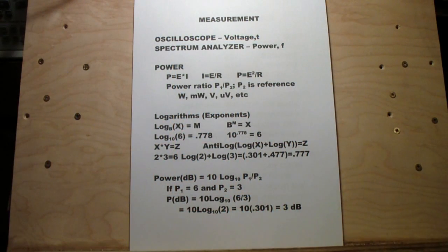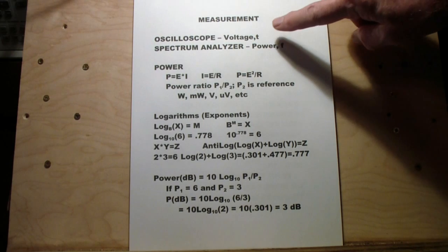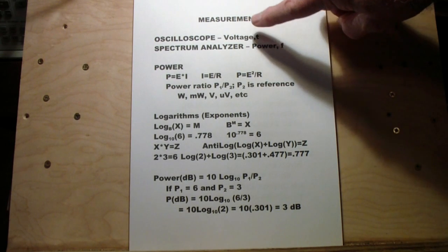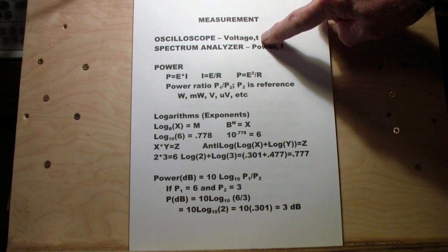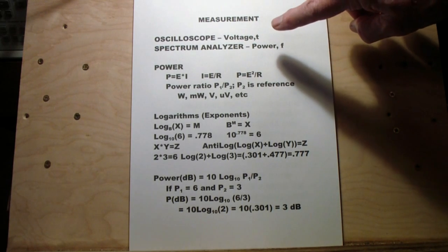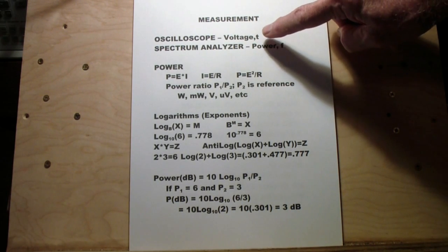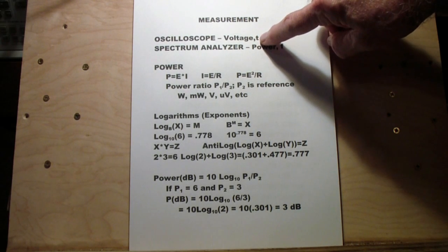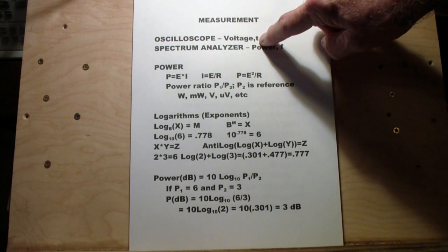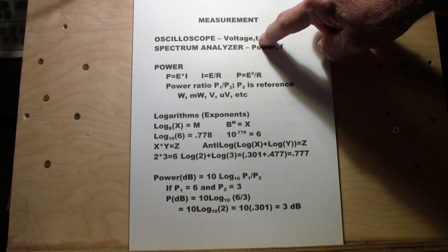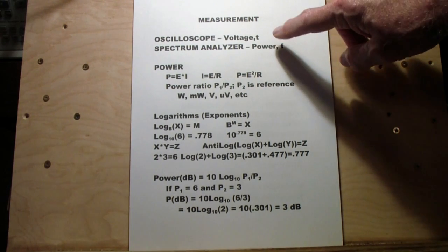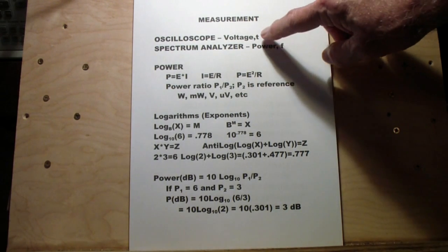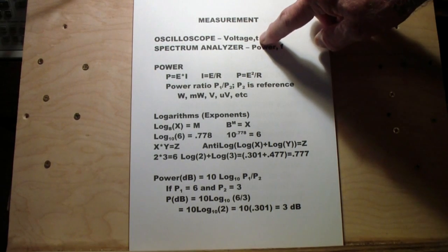So before we get deeply into some of the examples, let's make sure we're clear about what it is we want to measure. In an oscilloscope, normally what we are measuring is voltage and time. I know that a lot of oscilloscopes have a frequency measurement, but as most of you already know, all that really is, is they're measuring the time of a cycle, for example a sine wave, and then they are inverting that to get the frequency. That is, 1 over the period equals the frequency.